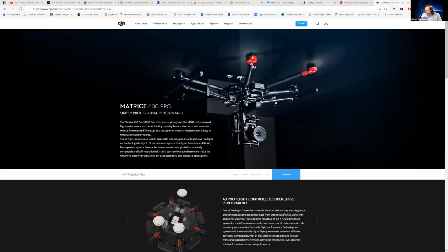Yeah, Jeff asked about the base station, like professional landscapers use for plats. Yeah, so you have a base station, they sell it, that integrates with the system, and your controller integrates those signals and sends out a correction. So when you're recording your photos, you're within a couple of centimeters. And what's more important, not the XY, is your Z, your elevation. If you can control your elevation within a few centimeters, your end product will be so much better.